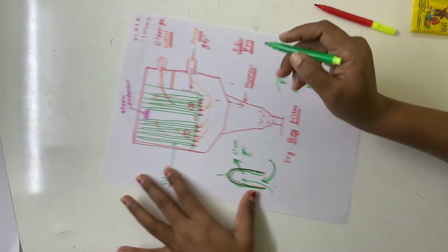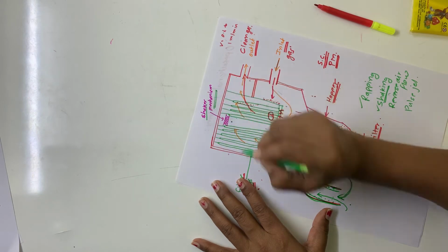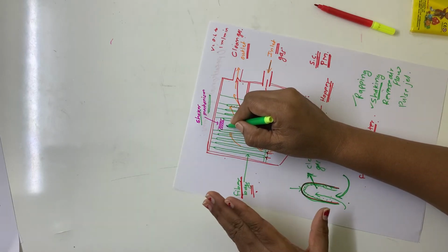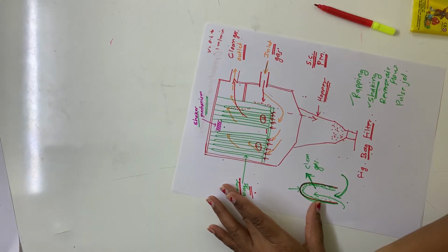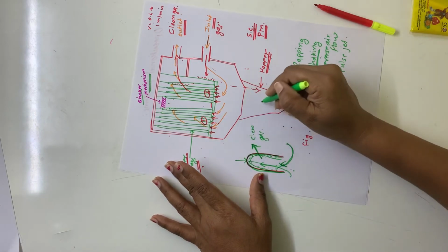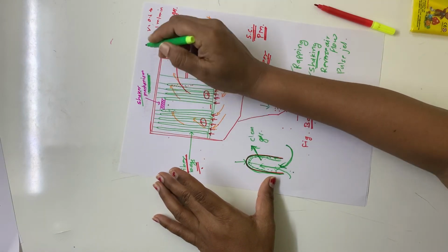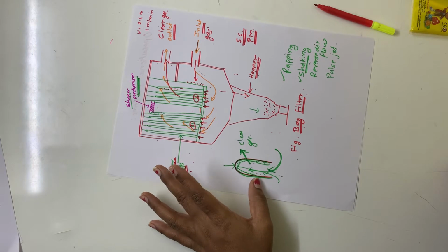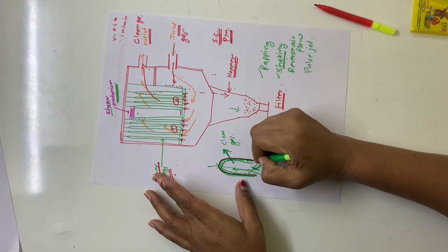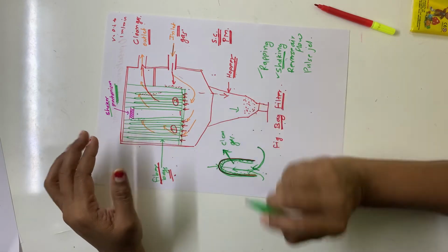So how can we use this? Here in this figure I have shown the shaker mechanism. You can add an automatic shaker mechanism here, and after some interval of time it will shake the entire bags, and while shaking, the particles attached to the inner wall will start falling down, and they can be collected here. So this way a shaker mechanism works effectively for cleaning the bag. And once you remove all these dust particles settled on the inner side, that bag will again come into operation for the cleaning of the next incoming laden gas.